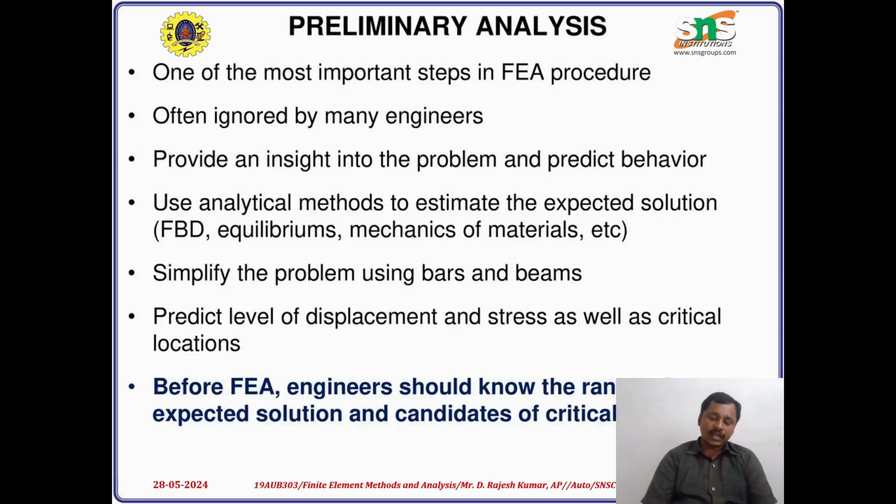The problem is also simplified using bars or beams. Here the problem is converted into a simplified element or structure, and then the predicted level of displacement and stresses, as well as critical locations, are found. Before FEA, the engineer should know the expected solution and also the critical conditions of the problem. That is the preliminary analysis.